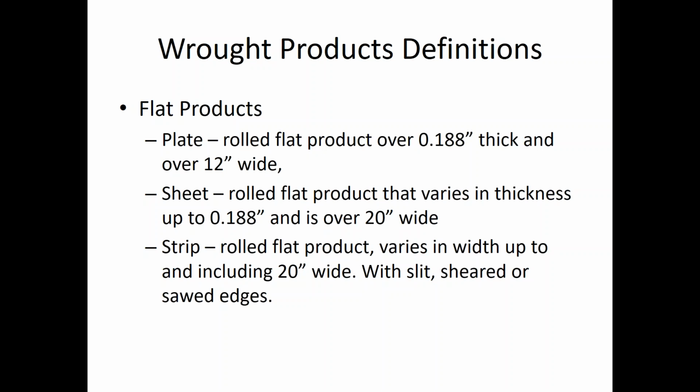Well, in wrought products, the definitions of flat products, I'd like to go over a few. Plate. Plate is a rolled flat product over 0.188 inches thick and generally over 12 inches wide. This is the accepted definition. Now people can define it different ways at different times.